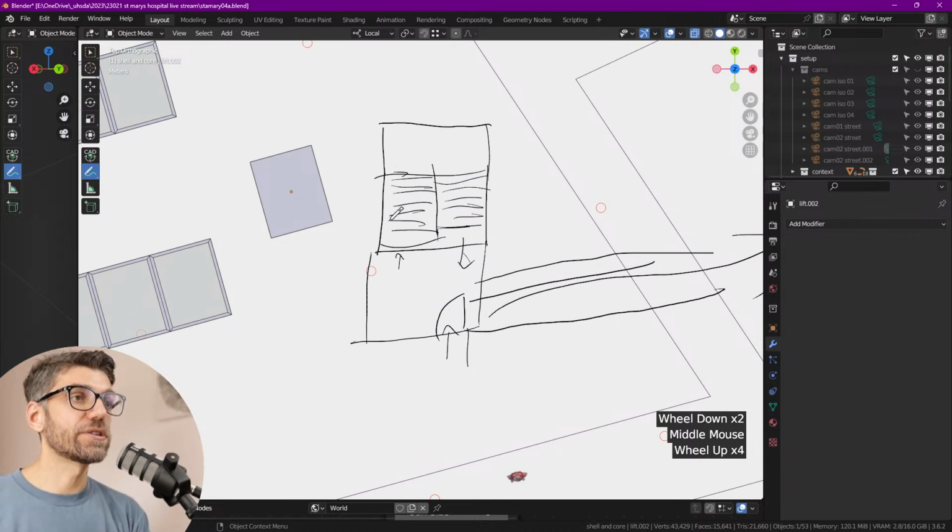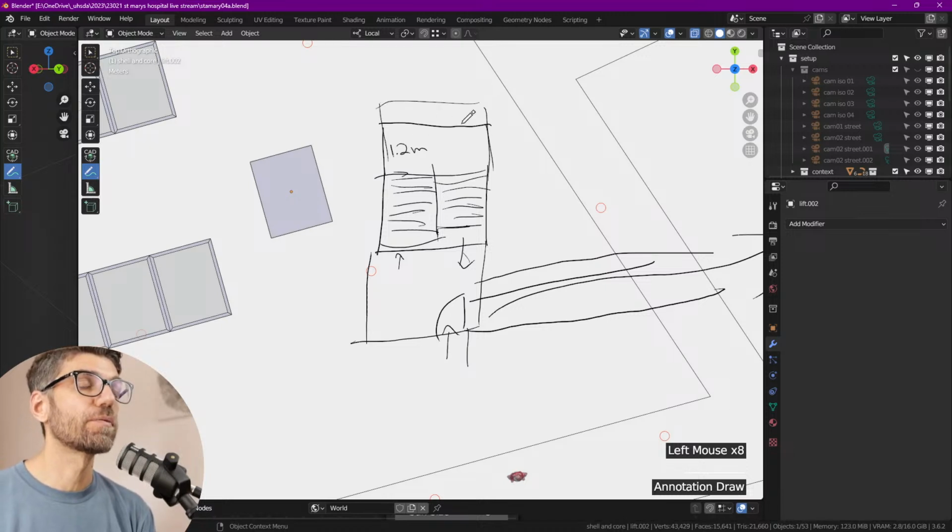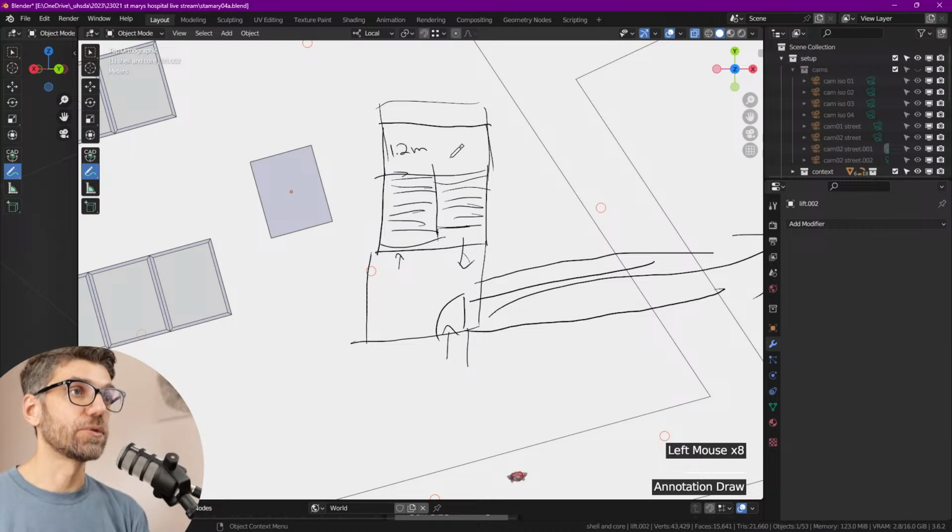And now about width. That's why I drew this more. It's about width. So this should be about 1.2 meters, I think is a good width. And the width of the stairs really depends on the population. So the larger the population, the more width you need, so more people can get down through it. So we got 1.2 meters here and then 1.2 meters here. Now that landing depth needs to be at least that distance, so it needs to be 1.2 meters as well.